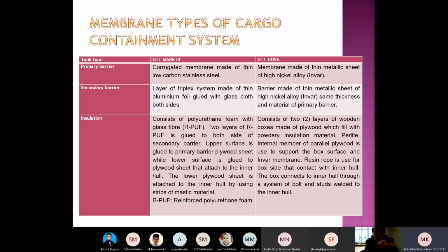Our main concern here, Prof, is more on the pressure, the impact pressure on the membrane, because a lot of failures happen. I think it was mentioned by Indo, Humaniza and Shiva, who have experienced one. So the pressure due to sloshing, and also ship motion combined, then we have resonance. So there's a worst case. That's why sloshing, especially for LNG, is considered important for people in the LNG business.